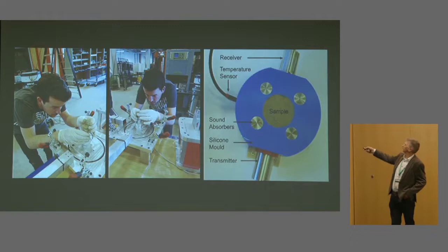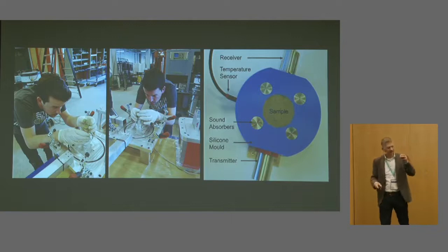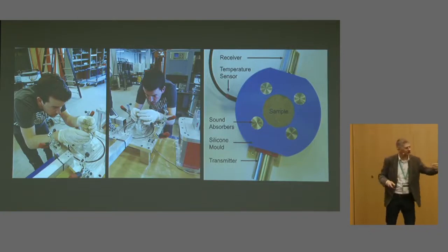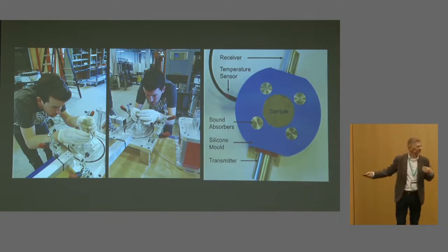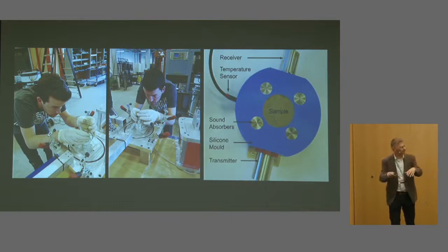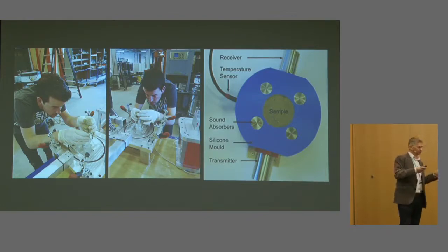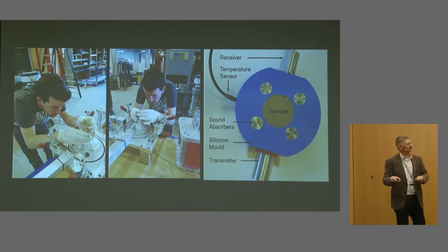And later on, we started to develop something completely different. We said, let's use a tool that is acoustic. Every time there's a piece of sound going from one side to the other side, the speed of sound is a measure for the strength of the material. And that's fun, because now we can mount that to our hose, and the concrete that flows out of the hose is tested on the spot. Every couple of seconds it is tested, and based on the transition of the speed of sound, we know the properties from one second to the other second and can be in control of them.